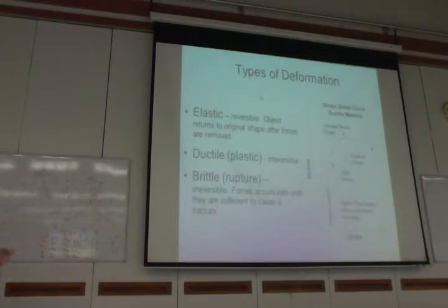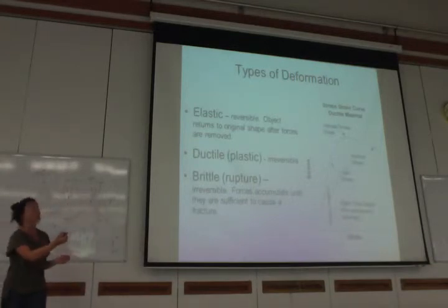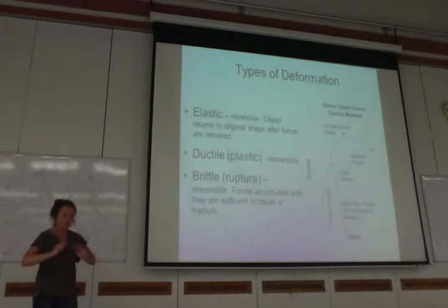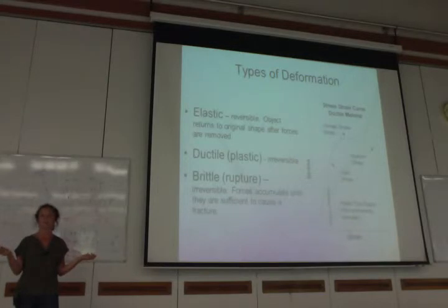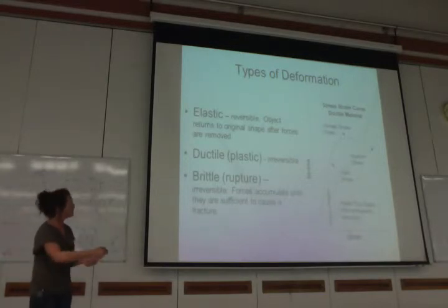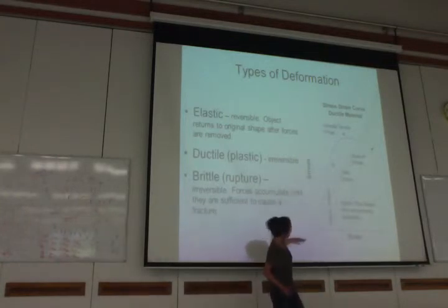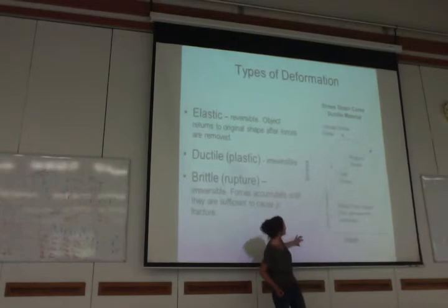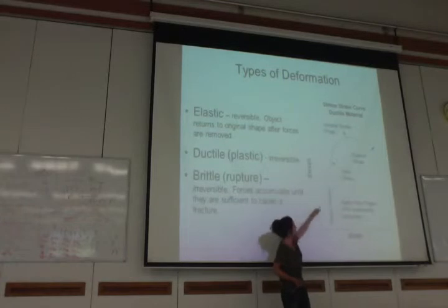And just to give you a brief background to strain and different strain types. So elastic strain or deformation is where a material, so a rock or whatever it is, responds to the strain by changing its shape or size, but then when you remove that stress, it goes back to its original shape. Okay? And if you're plotting stress, so this is the force per unit area, this is how the material responds. The elastic region, this is the first part of the curve, but if you take that stress away, it comes back.